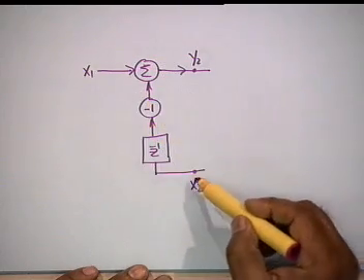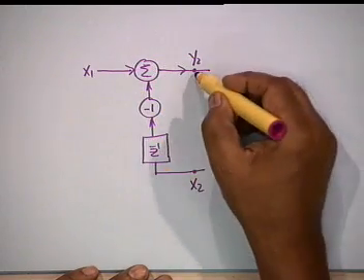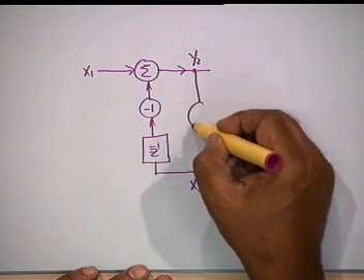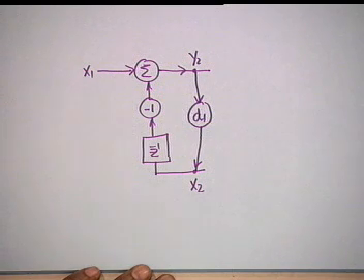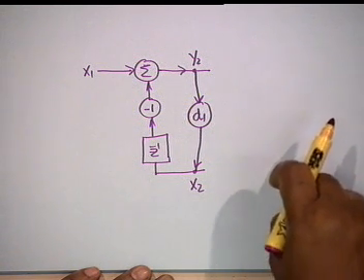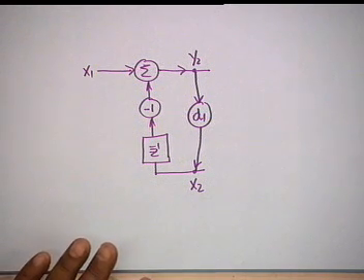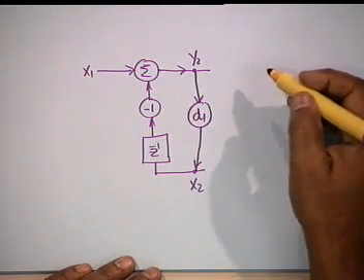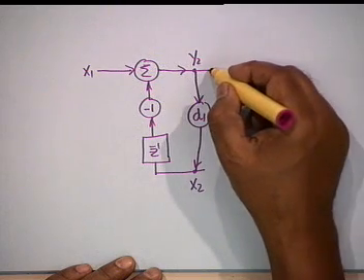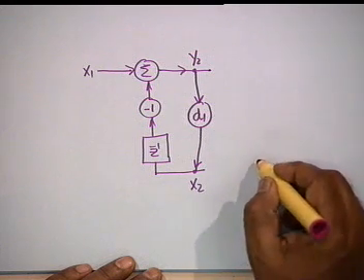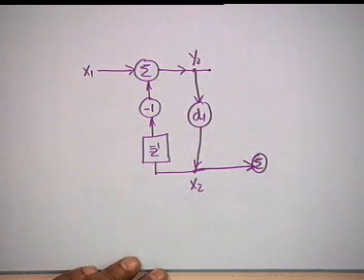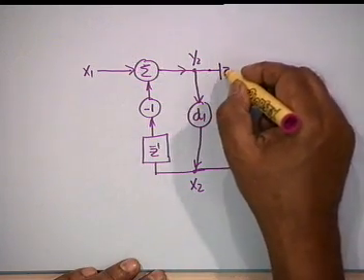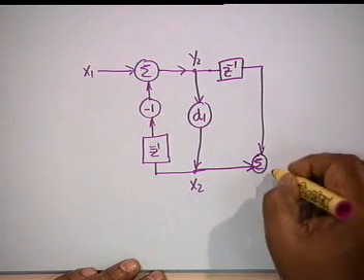x1 minus x2 z inverse will give me y2, but y2 and x2 are related by the multiplier d1. Agreed? This was a digital 2 pair terminated in multiplier d1, that is x2 is d1 times y2. Okay. Finally, we construct y1. For y1 we require x2, and z inverse y2. Is there any way that I can avoid this z inverse?